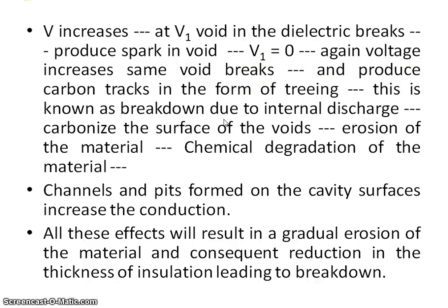Because of that spark, erosion of the material takes place, and chemical degradation of the material also takes place. Now the channels and the pits formed on the cavity surfaces increase the conduction. All these effects will result in a gradual erosion of the material and consequent reduction in the thickness of the insulation, leading to the breakdown.